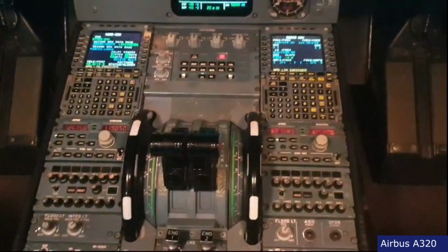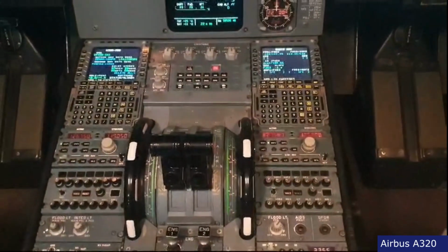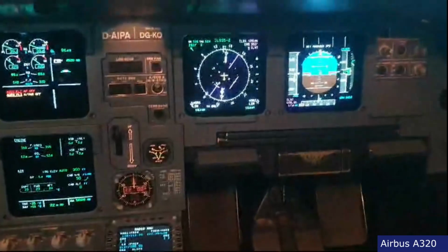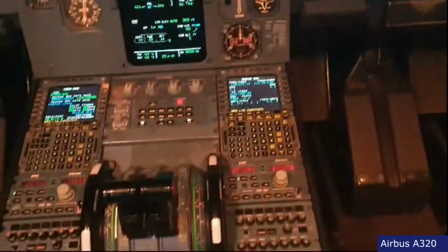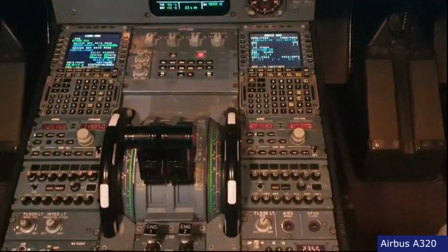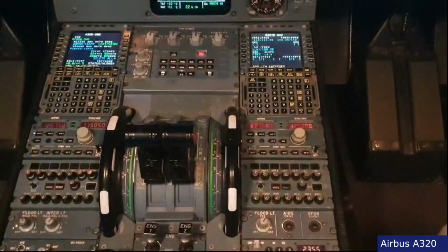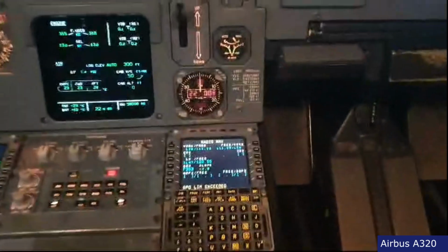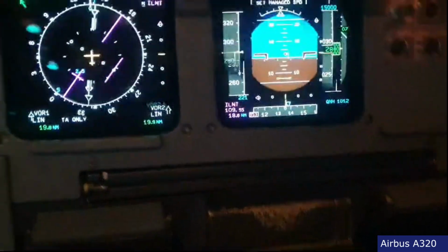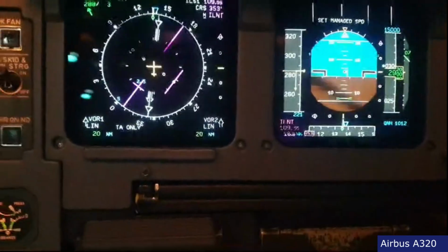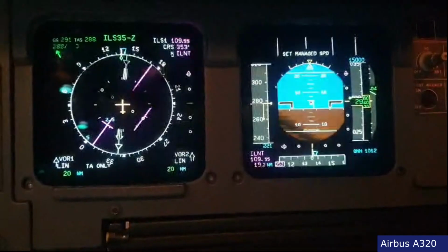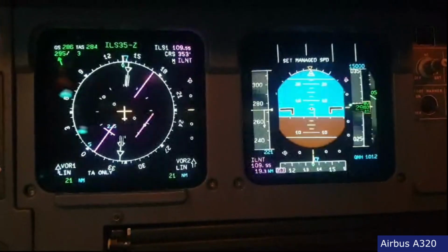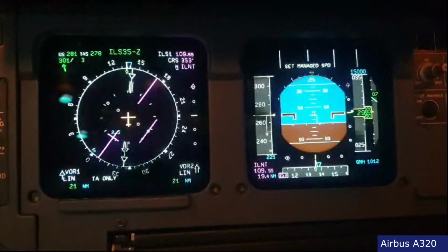Now here I'm just showing that with the thrust idle, the trim is moving nose up, so it's automatically trimming. We are keeping constant G acceleration on the aircraft. To keep a constant G acceleration, as the speed increases, obviously we have to reduce the pitch attitude. So you see now we're nearly 2 degrees and a half at 280 knots. Now thrust is idle, so we're reducing thrust, and again, to compensate the G, the aircraft is going again nose up.